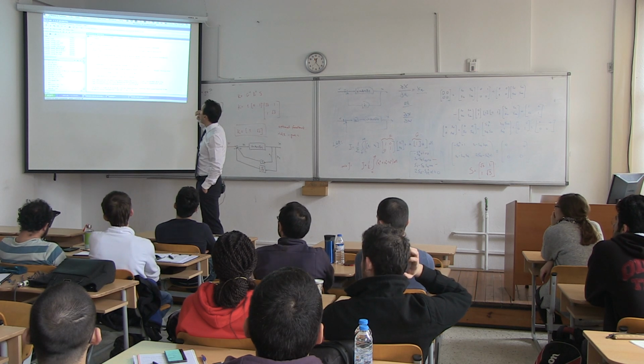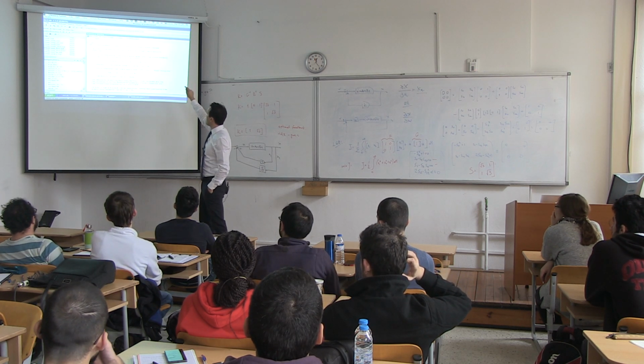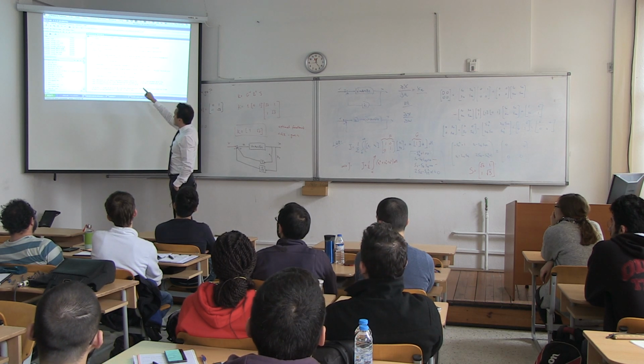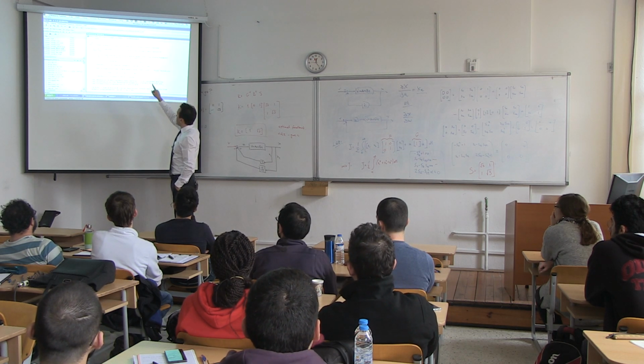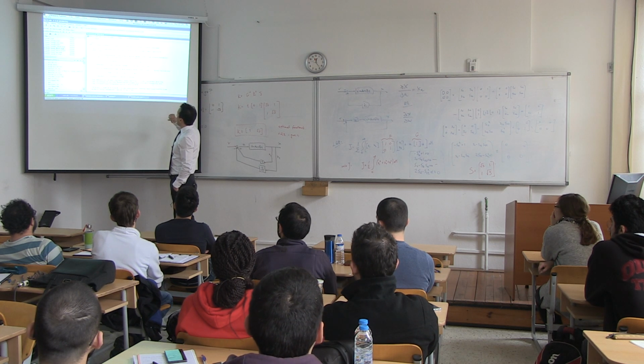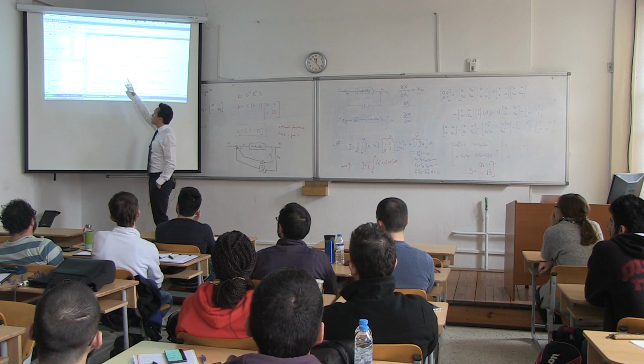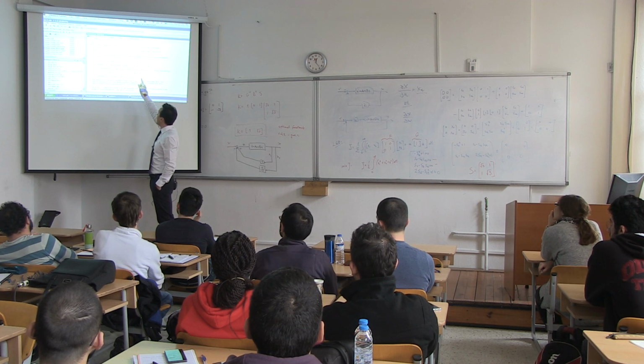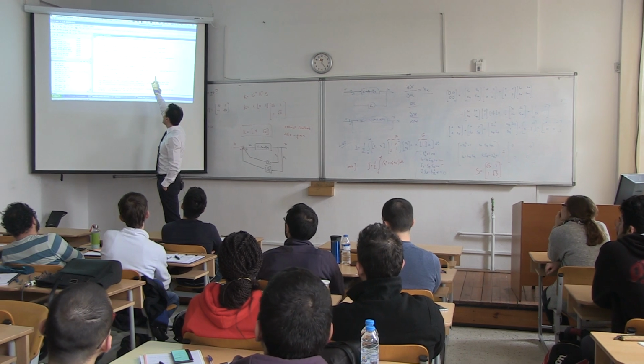It calculates the optimal gain K. For a continuous time state space model, the state feedback law is equal to u equals minus k times x, which minimizes the cost function. J is equal to the integral of x transpose Qx plus u transpose Ru plus the cross terms 2 x transpose N u.